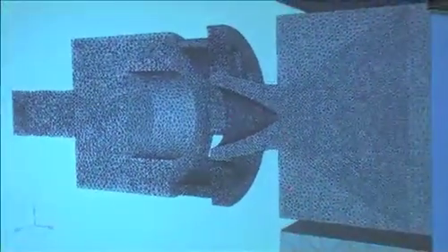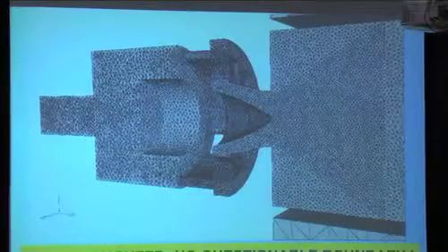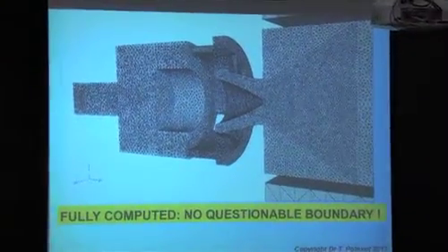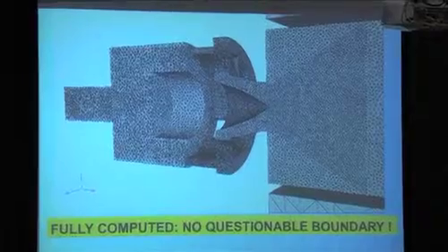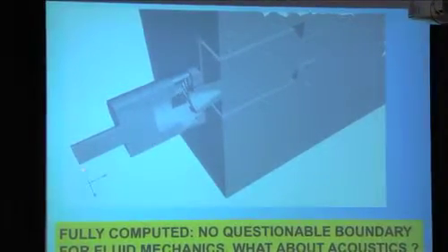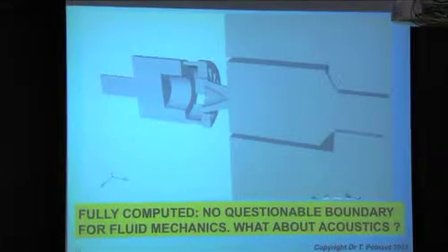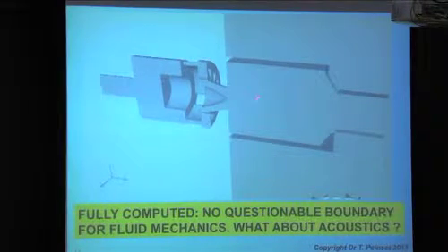Okay? Fortunately, when you go from 1 million to 10 million to 2.8 billion, the results don't change that much in the field of thermoacoustics. You just wait longer. Well, not really, because the computers have improved too. The nice thing about this computation setup is that there is no boundary condition to set up except to say that the pressure here is 1 bar and the flow rate here is imposed.